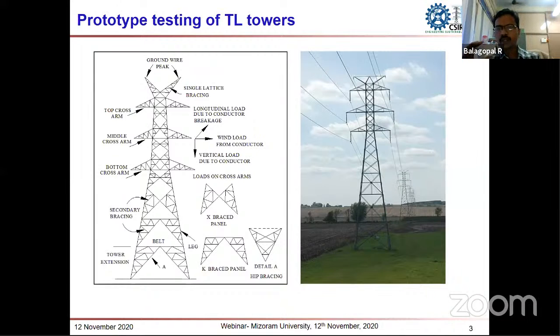The main advantage of this hydraulic ram is that we can apply the load in a very smooth way. That is, without any jerk, the loads can be applied. And if we notice any failure during the testing of these towers, we can stop the load at any point. That is one of the unique facilities we have. Hence, clients from all over the world prefer to test their towers in our test bed. I will talk about what are the facilities we have in the next slide.